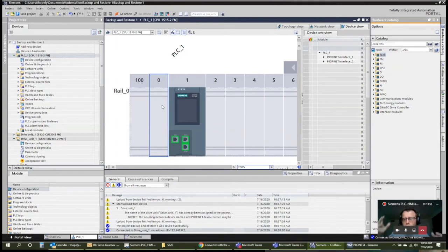And there's also a whole bunch of other functionality built into Profinet, like Profinet device names and device swapping, module swapping, which are things that are typically supported by Profinet, but not by just Ethernet. It would have to be a Profinet port. So there are certainly differences, and the key to remember is that just because you have an Ethernet port doesn't mean it necessarily supports Profinet.